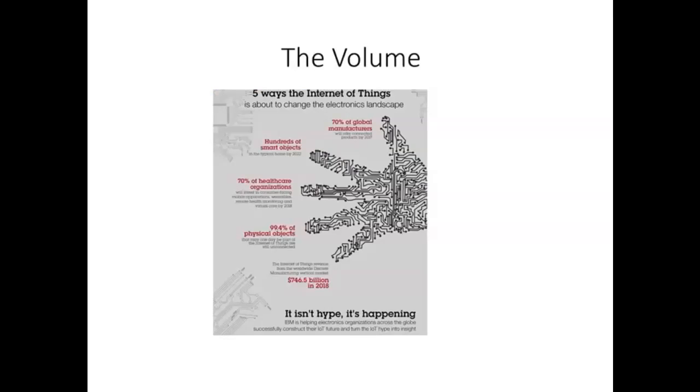Our device, when I talked about the ability of hooking up third-party peripheral devices: lots of tenant improvement or construction happens in hospitals, and the one biggest thing about hospitals is contamination. So what is normally done is sealing of areas when there's construction, and a negative pressure air situation is needed to make sure that it's completely separated.